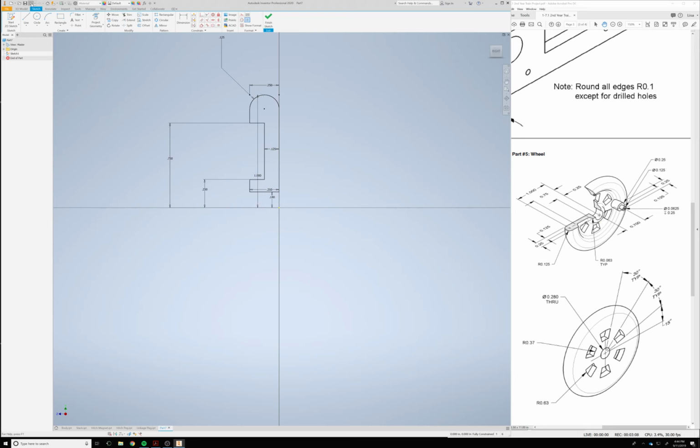let's go. I'm going to undo this real quick, and I'm going to delete this dimension, our overall dimension of 1. I'm going to again do this where I have this fillet and this fillet, and I'm going to leave it at that. I am then going to change our fillet radius to 0.063, and we're hitting all of these corners on the inside.